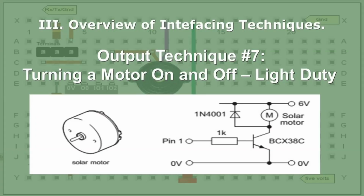Now here's the big daddy, when you want to turn a motor on and off. Again, notice the diode is across the motor for the counter EMF, so when you turn the motor off, it doesn't produce a reverse EMF across it. Because remember, the motor is an inductor. What's going to happen when you turn the power off? It induces an opposite, a counter EMF right across the windings of that motor. So you need a diode to clamp that reverse voltage.